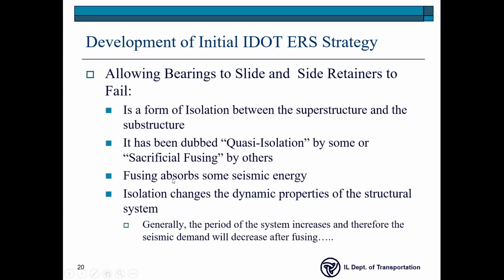This fusing, between the deck and the substructures, does absorb seismic energy, and it also changes the period of the structure itself.